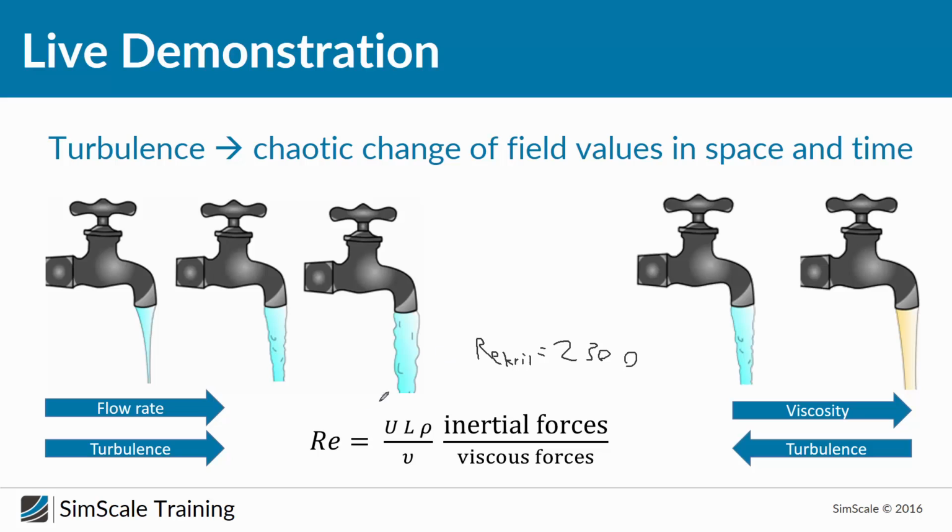Another very important thing about the Reynolds number is that it allows you to compare flows or aerodynamic tests. That's the reason why the Reynolds number is very important for wind tunnel testing. Two objects, or let's say two scaled models, with the same Reynolds number will have the same behavior. That's the reason, for example, why you can use a 50% model in wind tunnel testing.